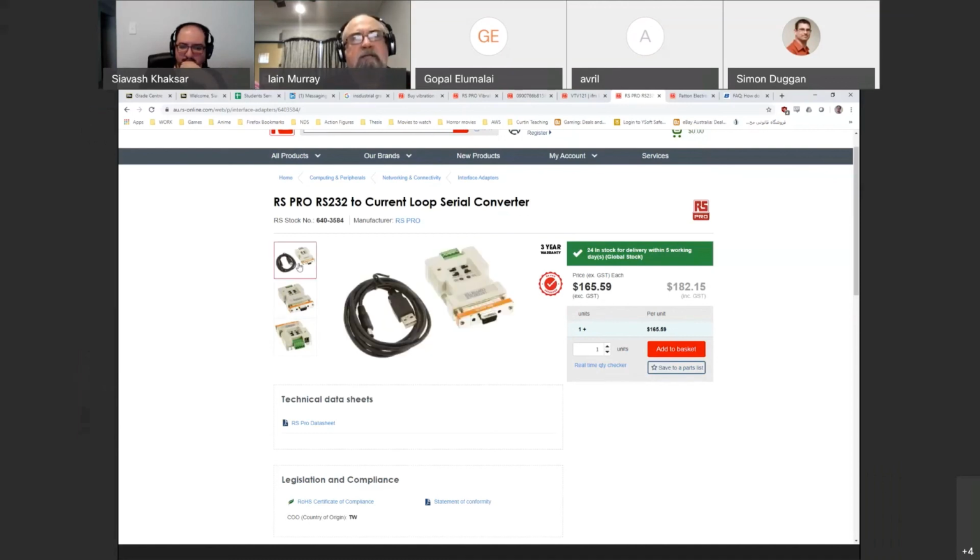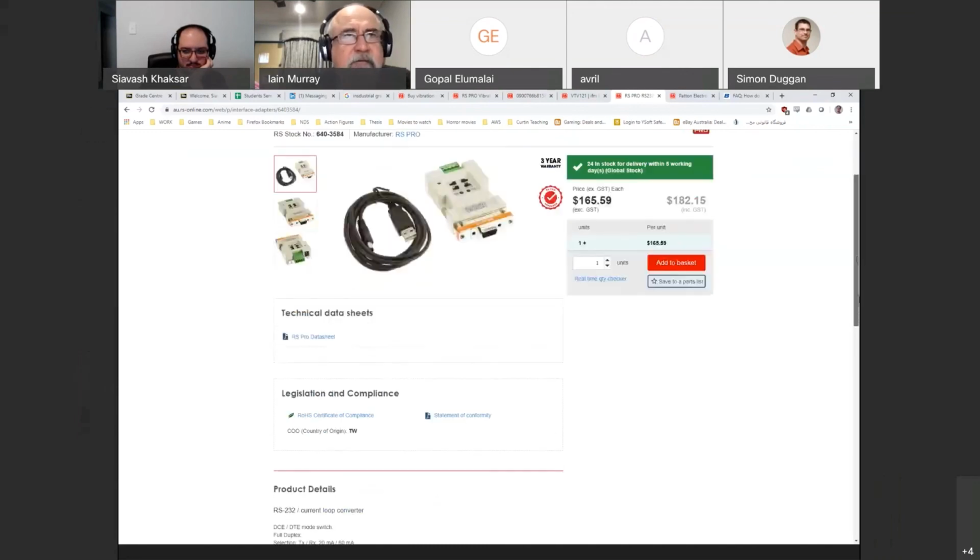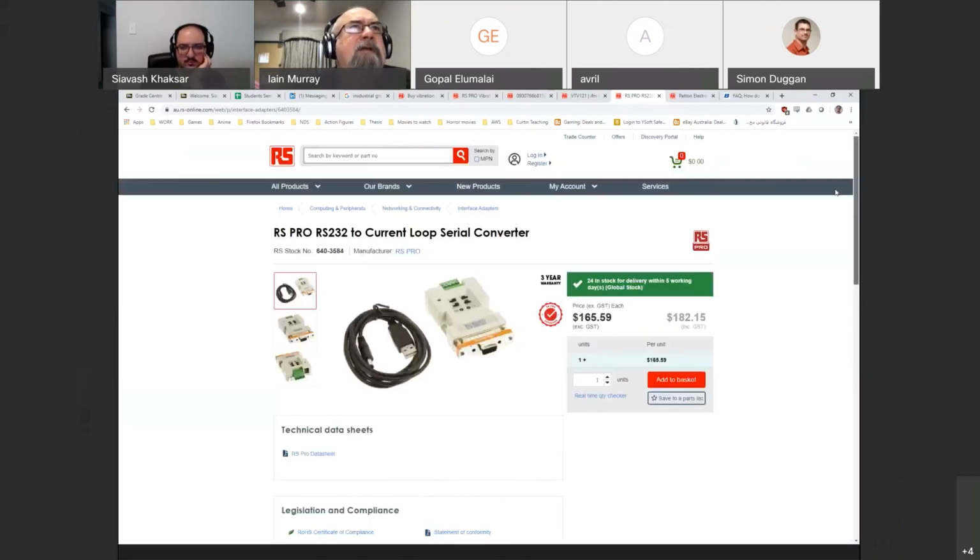Now, that said, there's something else I can mention on prototyping, and that is the simulation of sensors, particularly in a case like this where there is very limited time and, in many cases, very limited funding. If you've got something like a vibration sensor that's very expensive and has to go through this conversion process, consider using a small, cheap microcontroller that will randomly, but within range, generate the kind of output you would expect from the sensor.